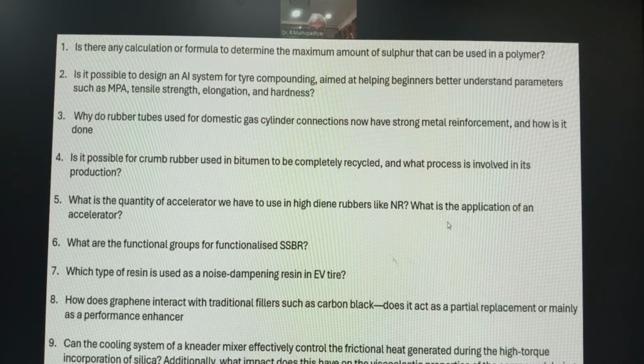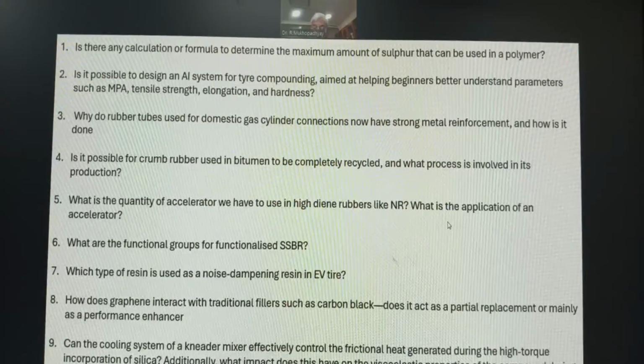Then you have to give your input, like your materials, what is the phr of the different ingredients, and out of the ingredients, the polymer behaviors and certain polymer characteristics. If you're using solution SBR, functional SBR, and so on. If it is carbon black, their surface area, particle size, the curing, all that is certain data: slow accelerator, medium, fast accelerator, and so on.